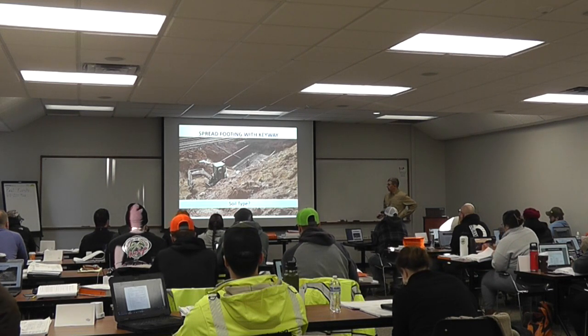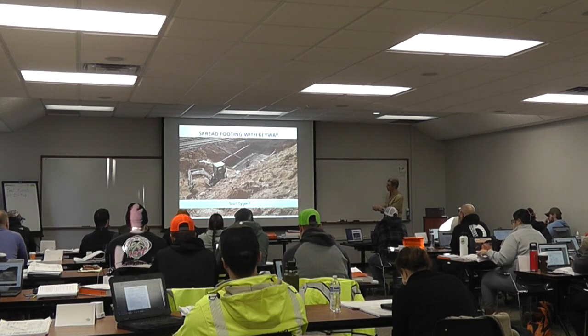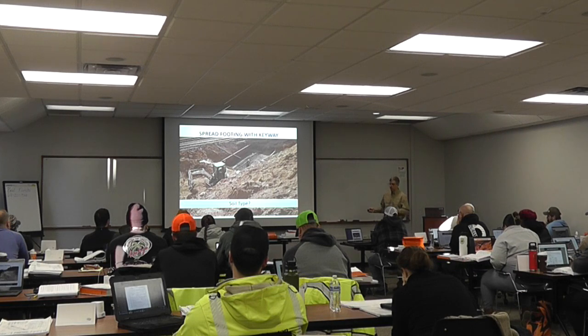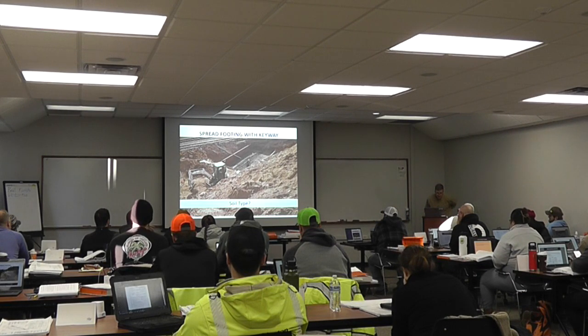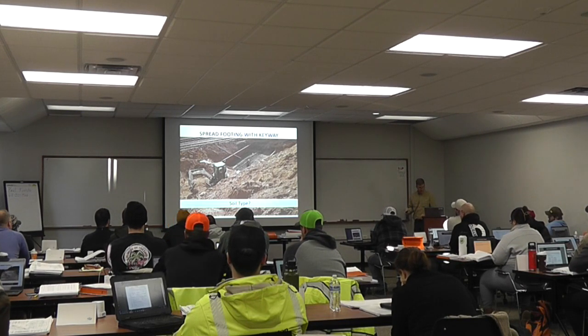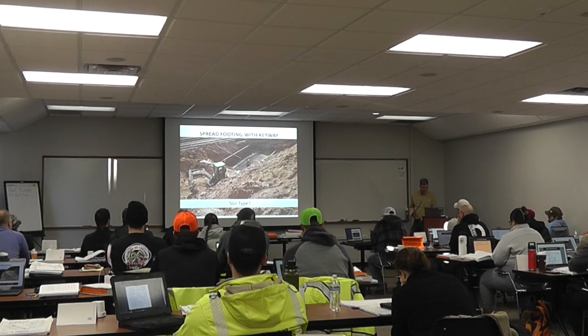You can also look, of course, at the soil type. This is a case where we're building adjacent to a railroad, so as you're building, make sure that whatever provisions are required for the railroad are followed. It's kind of a weird picture. It looks like you're almost right on top of the railroad, but it looks like maybe it is up an embankment and it's far enough away. But make sure whatever protection for the tracks is required is done.